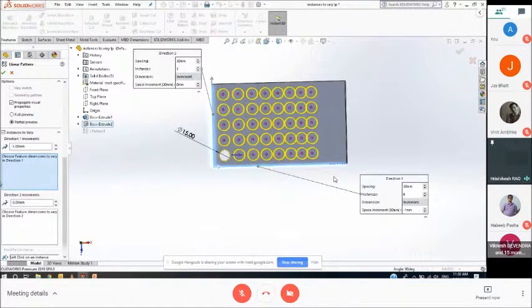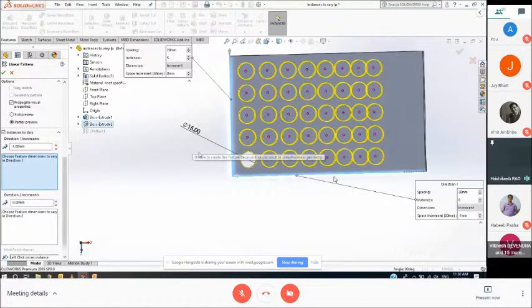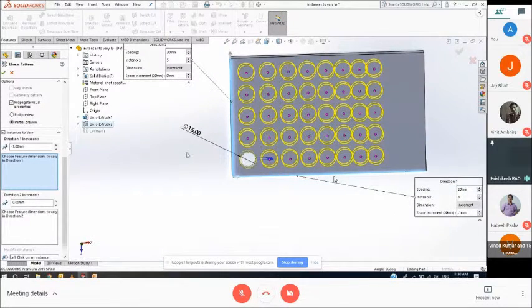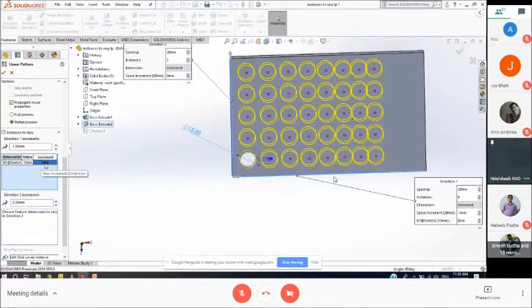Here in this box, I can select the feature dimensions which I want to vary. For example, for this cut section, the diameter of this cut section is 15 mm. So I'll just select this dimension. And if I want to increase that dimension, I can just input as 1 mm. For this instance, I want to decrease this dimension by say 1 mm or say 0.5 mm.